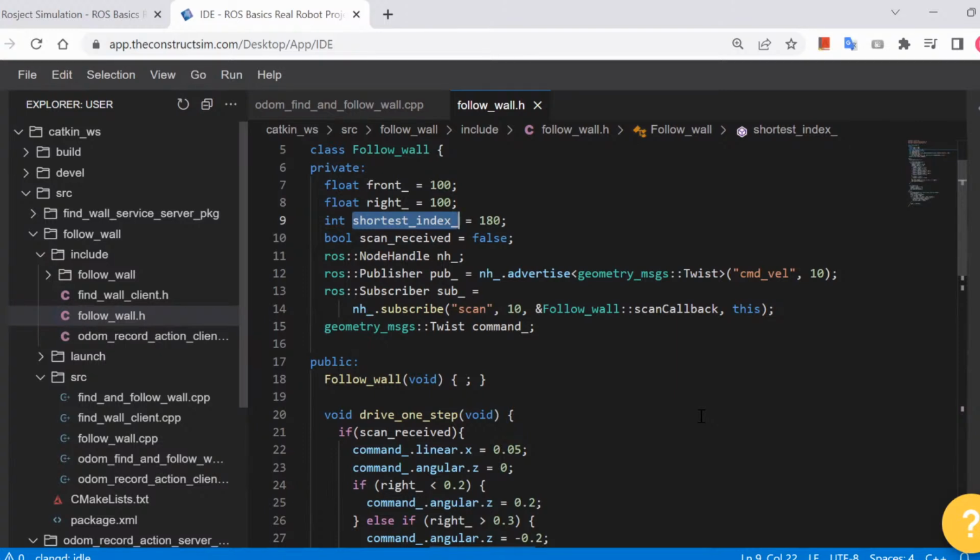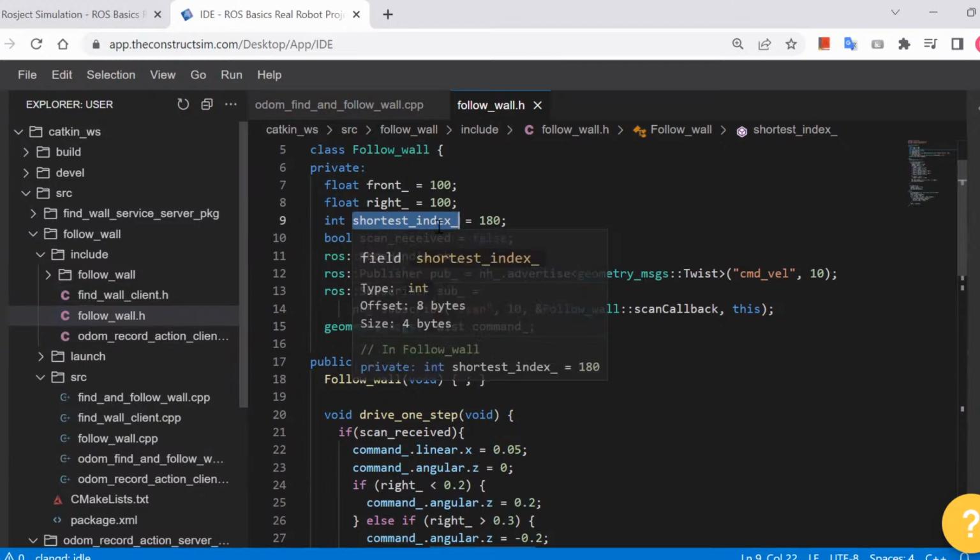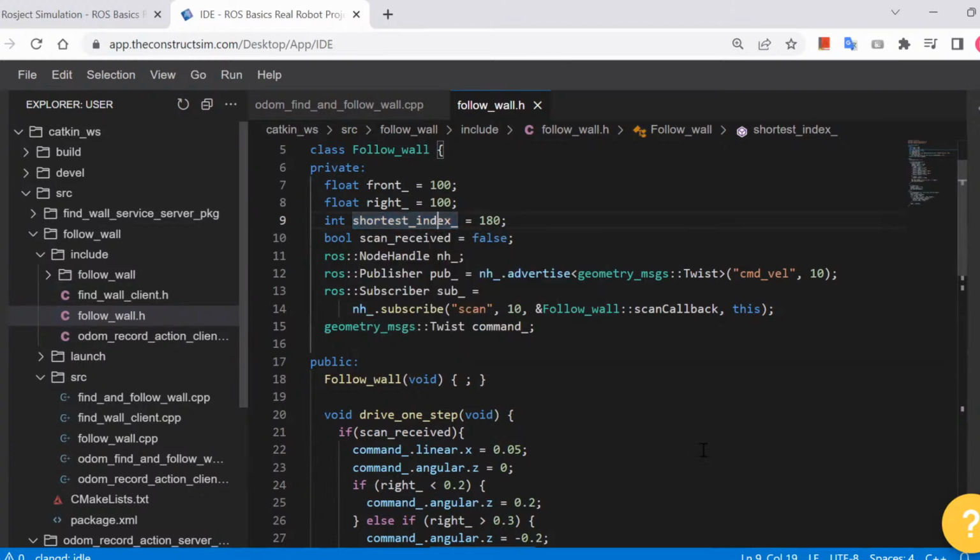By the way, I don't know if I should remind. So for this scan, the laser scan result message, for this robot we see the index, which is all the data inside the message. Index goes from 0 to 720, to be more specific, 719. So that's 360 degrees around the robot.